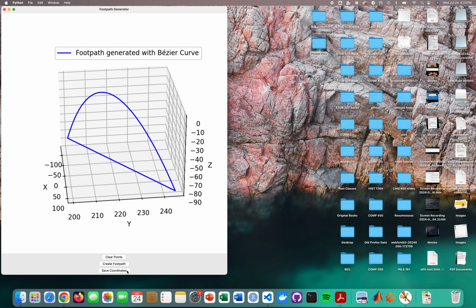Around this point cloud, we created a convex hull, which is a polygon. And then once you created the convex hull, as you can see right here without the point cloud, you can test to see, is a footpath coordinate inside this hull or outside? And so that gives you very good information about the footpath you've created.